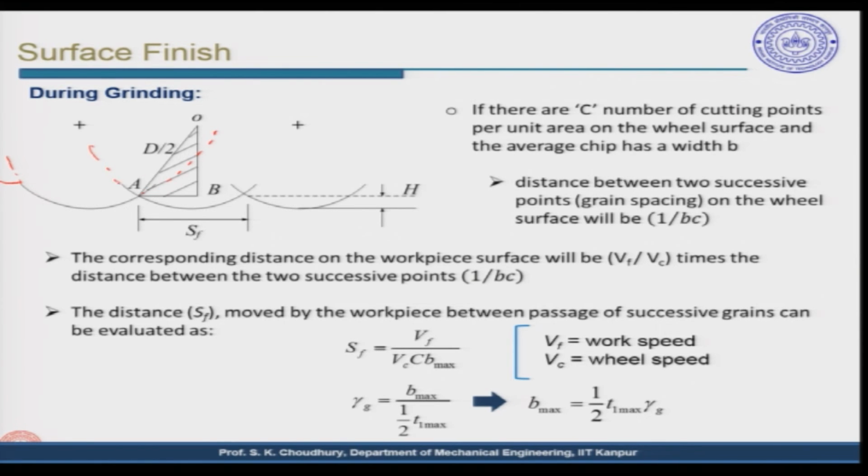This is the earlier position of that grinding wheel, and this is another position of the grinding wheel. So, these are the centers of the grinding wheel, all right. Therefore, the workpiece that we will be getting will be something like this, and on this workpiece the Vf is given, that is the feed velocity.